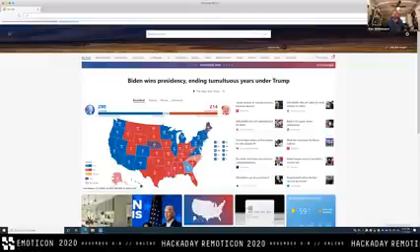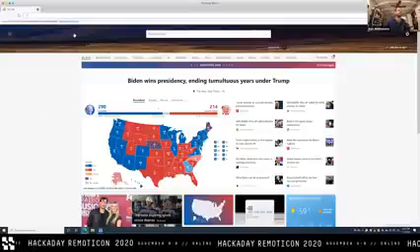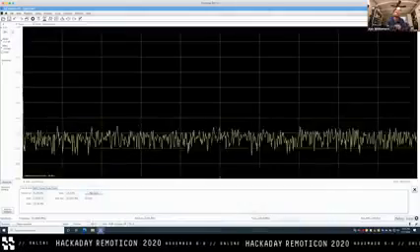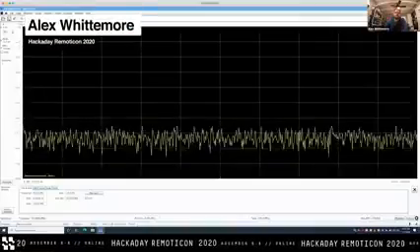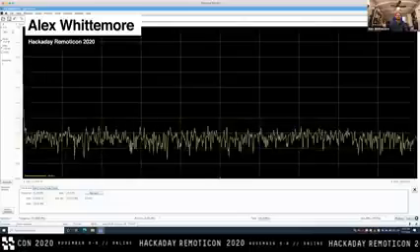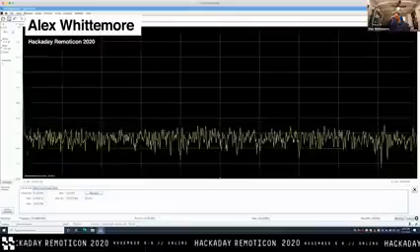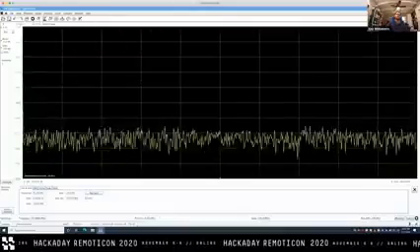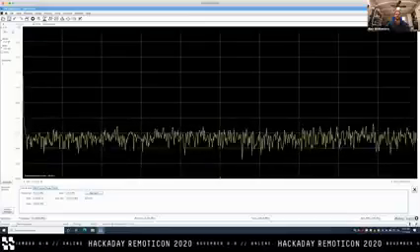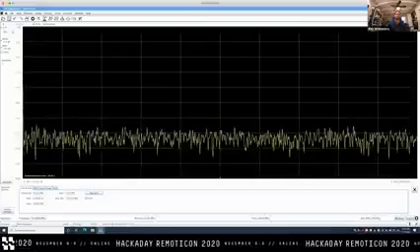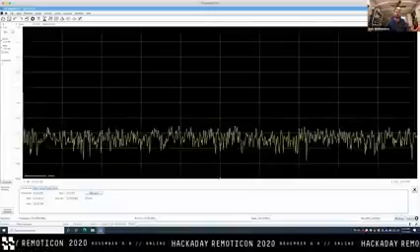If you've got multiple devices operating on that same circuit and you need to time synchronize them, it blasts a 60 megahertz clock out on one of those pins. So that's probably what we're spotting there. And now you just go look at the pinout for the device and see, okay, is that what I'm seeing? Is that signal that I know exists in another part of the chip coupling on to that signal that I was measuring erroneously, or what's going on here?